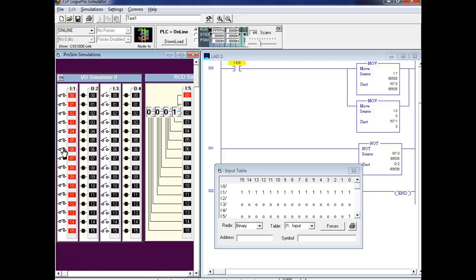I thought it was closed. Yeah, so I had my hand over there. So let's go back and rephrase it. So when the switch is closed, I have a what? 1. So maybe that's why you're so confused. So if it's closed, I get a 1. So what's it hooked up for? Sourcing. What we're doing is, if it gives me a 0 when it's closed, it's hooked up syncing, right? You understand? If I get a 1 when it's closed, it's hooked up sourcing.